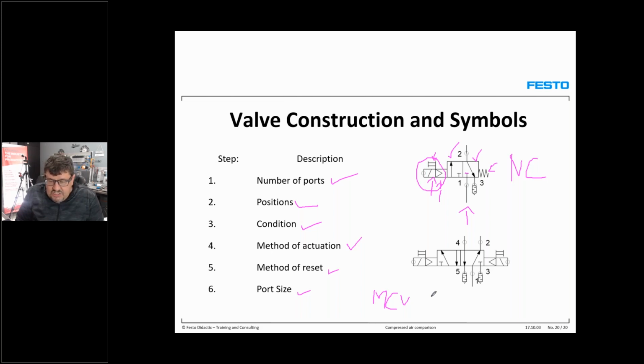There's also a 2 on both sides. There is your manual override. On both sides, we got your internal pilot lines. And then that means when you want to identify this valve or describe this valve to somebody, it's important to understand that you cannot tell them that it's normally open, because it's open in both the 2 positions, on your right hand side or your left hand side.